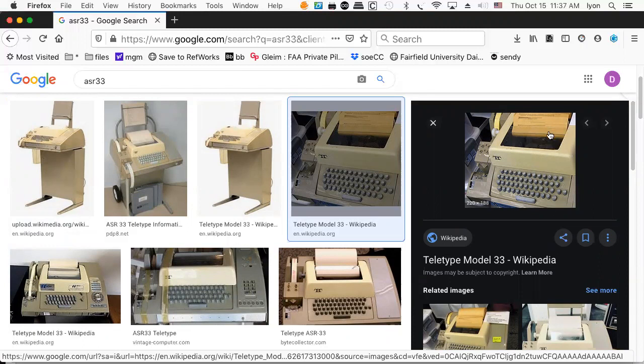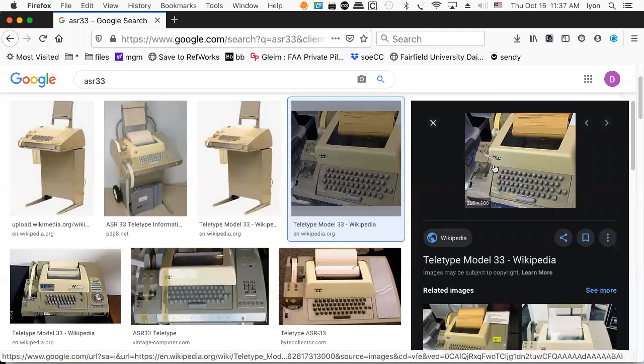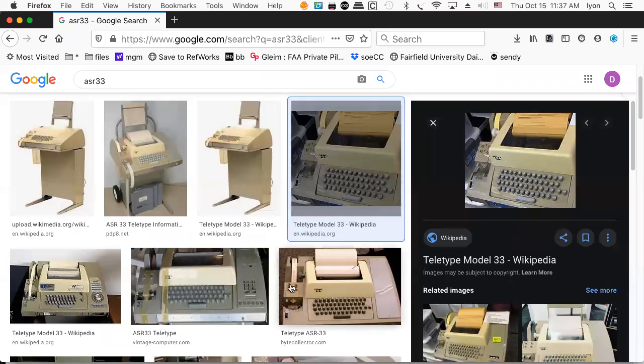So advancing the platen, that's a line feed. Getting the carriage to go all the way to the beginning, that's a carriage return. So you do line feed first and then carriage return. Actually, you do carriage return and then line feed, because carriage return takes longer. These things would print at 10 characters per second, but they had the added advantage of also being able to punch out paper tape, which would be good for long-term storage. I still have some paper tape in my garage somewhere.